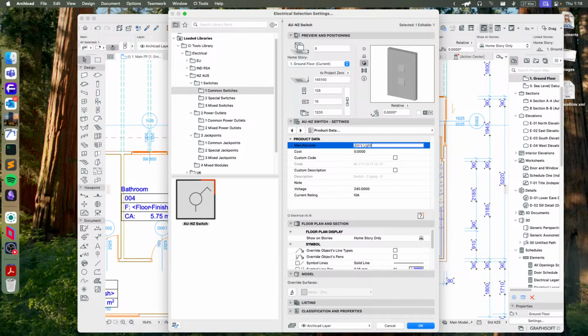As you may know, with ArchiCAD 28 moving to the libpack format for libraries, which we can see in our library manager, if you migrate an ArchiCAD 27 or older project, you'll still be using your old LCFs rather than new libpacks. In most cases, you will want to keep doing that. You'll want to keep loading the old LCFs.